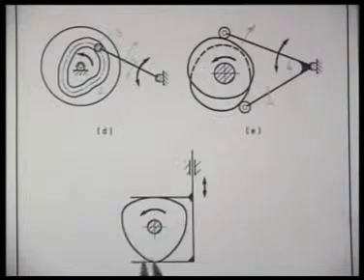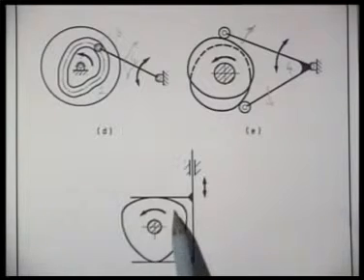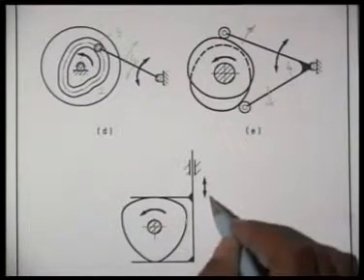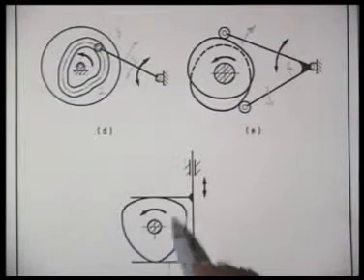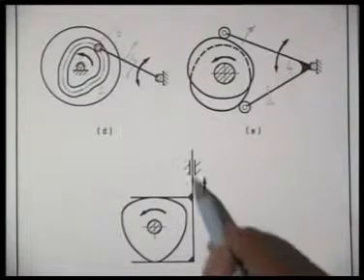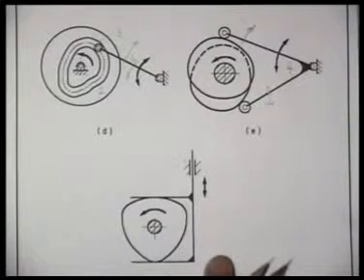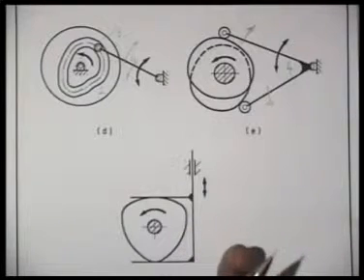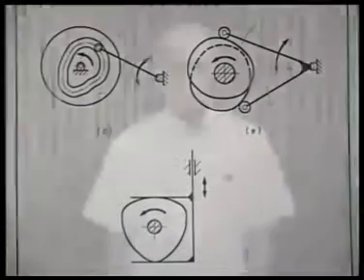Similarly, here we have what we call a constant breadth cam. The cam profile is such that it will be in contact at both surfaces, so both up and down motion can be ensured by the rotating cam. No need to use a spring. This is called a constant breadth cam. But we will restrict our discussion to the cams where we shall assume there is a spring to ensure contact during the entire stroke of motion.